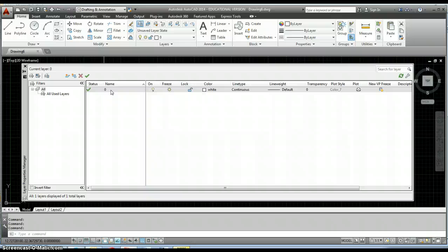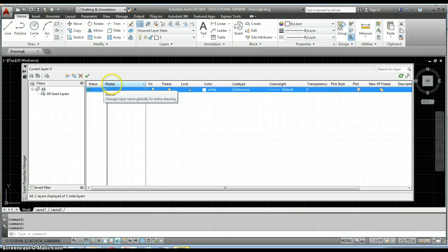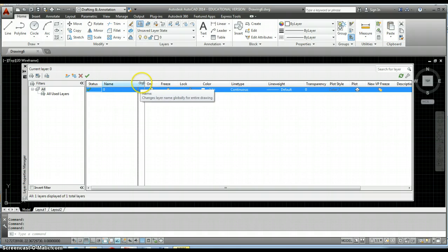And so right now just go ahead and take a couple of minutes and pause this if you need to, just to rearrange your columns by dragging them so that you can see all their names. So you can hover over the little vertical line in between columns and then left click and hold it down, and you can drag it to resize the width of that column. So go ahead and do that for all of your columns so that you can read the top of the column and see what's in each of the cells.